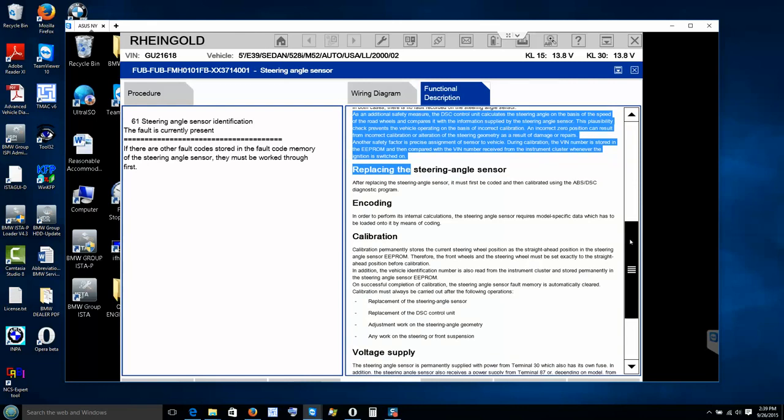All right, but the main information that it compares now is the VIN number. The numbers are close. I understand, but I'm just saying because you went through everything and we look at it and when you turn the steering, you can see the steering angle and everything moving. So we know we get a reading from that. If it wasn't getting a reading, then we could say, well, the sensor is bad. Right? And you went through the programming and then it's still telling you that something is wrong with the sensor.